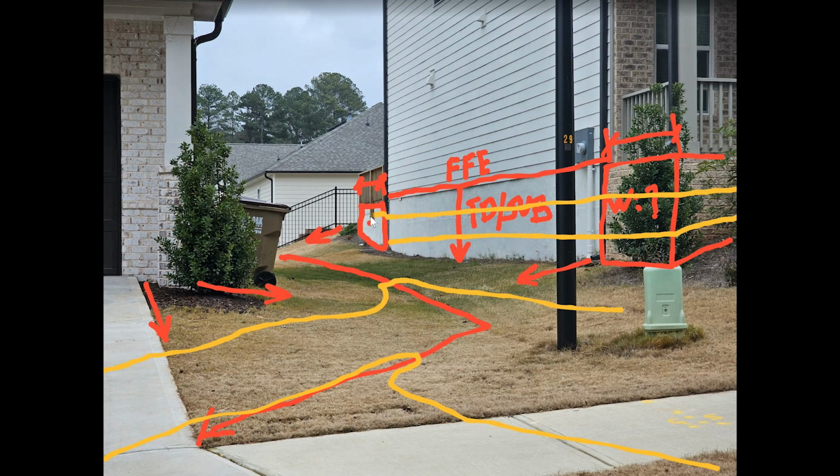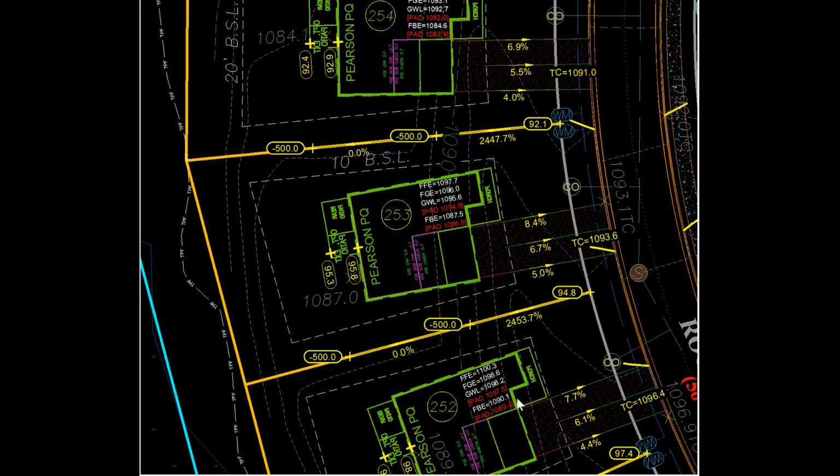And then what I'm doing here is just showing that the contours, obviously it's a wall to a building. The contours are still going up that. We generally don't show the contours once they hit the wall. We don't show those unless it helps with our surface modeling. Sometimes we'll use break lines or something to go ahead and make that work instead.